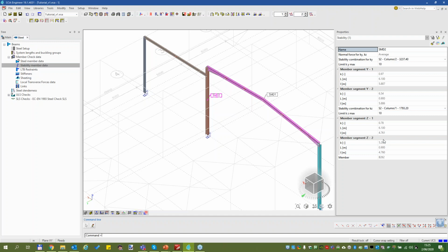If you just do a linear calculation, so without stability, without second order or anything else, it will use a different approach, which has its limits. The main limit is it gives good results for moment rigid connections, columns or beams connected with moment rigid or semi-rigid connections, and that are under an angle of approximately 90 degrees, perpendicular. If you don't deviate from that, it gives proper results.